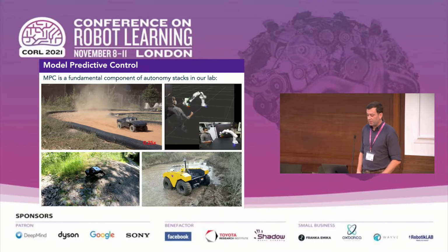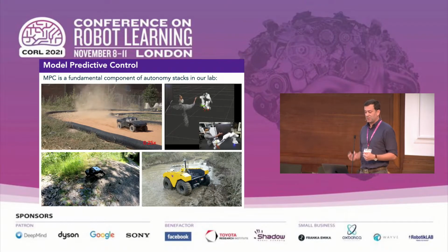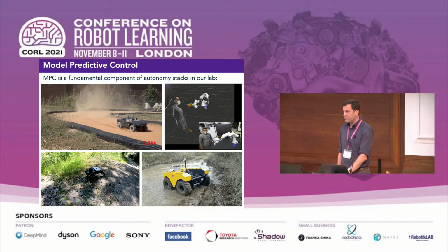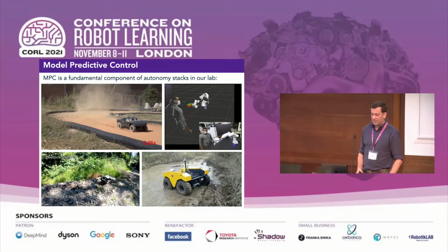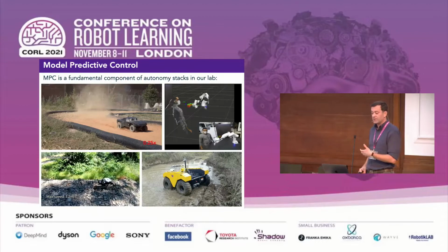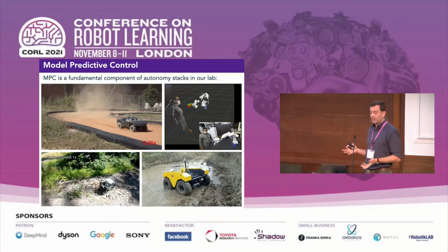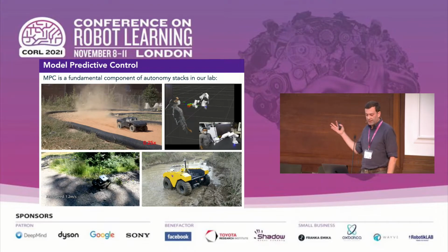More recently, we've been using MPC to control 7 degree of freedom robot arms that are interacting with unpredictable humans. Here we're optimizing for trajectories in configuration space while estimating the changing state of the world in real time. As you've seen earlier today from Yu Sheng's presentation, MPC is also a powerful tool for locomotion. Here we're using a low-level MPC strategy for torque control of a quadruped. It's solving a constrained convex optimization problem at a really high frequency, allowing the robot to contend with uneven terrain like the loose rocks as it scrambles along the edge of this path.